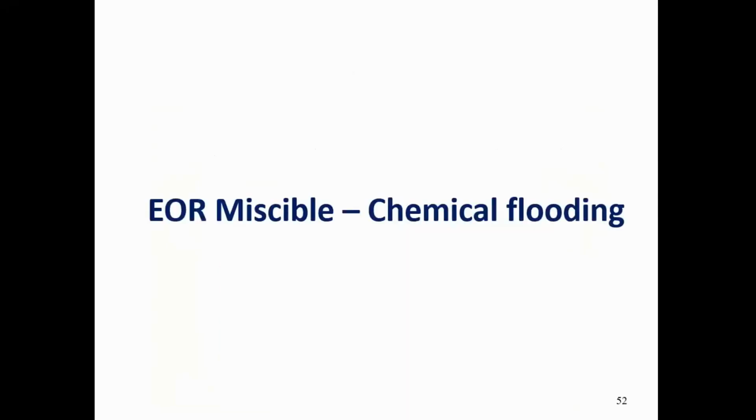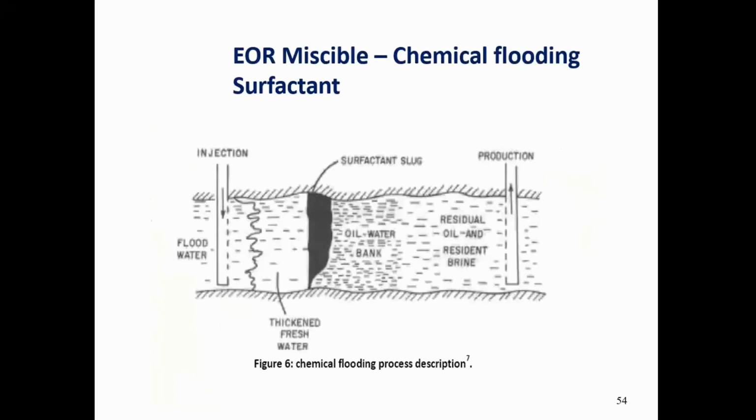I will use only one example of chemical, and then I stop. So chemical flooding, tertiary recovery, they sometimes use surfactant. Surfactant is soap, washing liquid. Same as any washing liquid, you mix it with water. For every bottle of water, you put almost 1 kilogram of surfactant liquid, mix it very well, and inject it in the injection well. So now you're injecting soapy water.